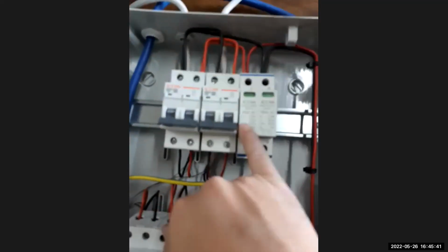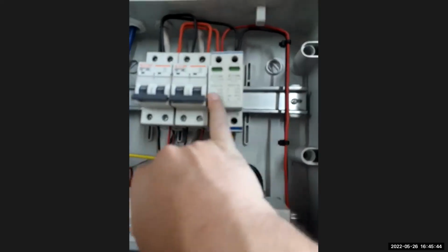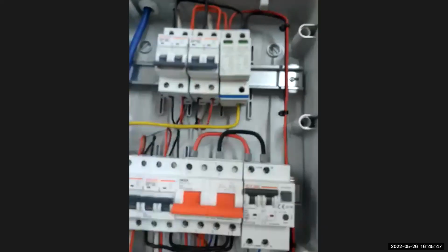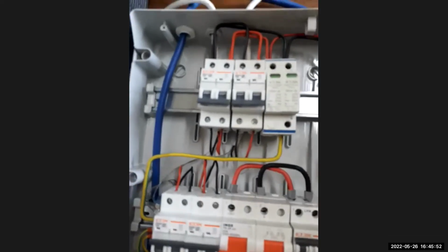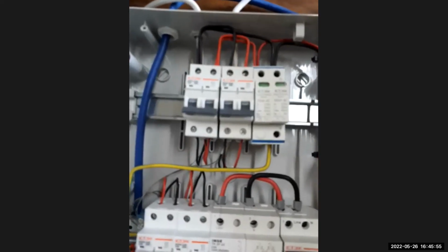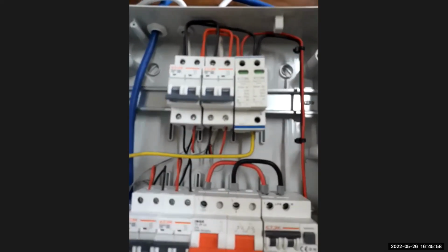But this is a 275 volt SPD, my SPD on the input side. So my SPD will melt and throw all the current that's going through it, through the earth, away before it will damage the inverter. So that's why we always recommend you insert an SPD in your line to protect the inverter. So these two inverters won't get damaged through what you just told me, because I have the right protection devices built into my AC box to protect my inverters. Thank you.